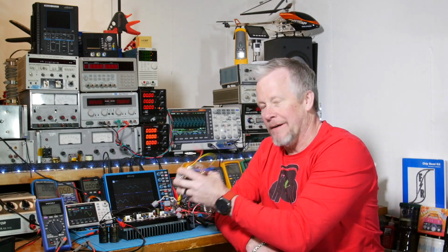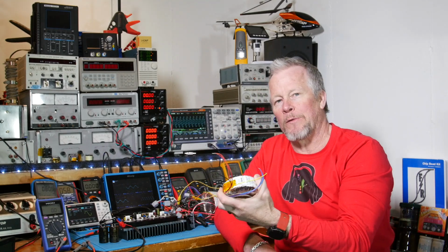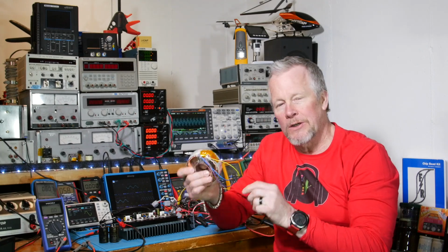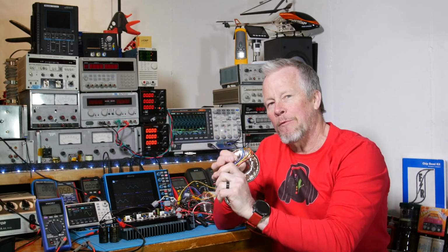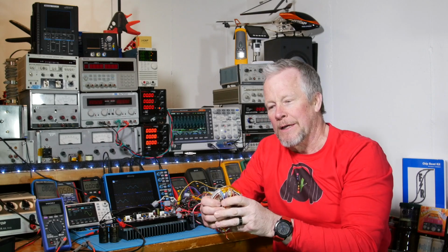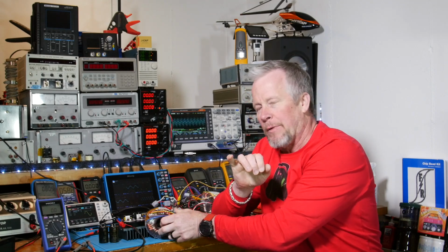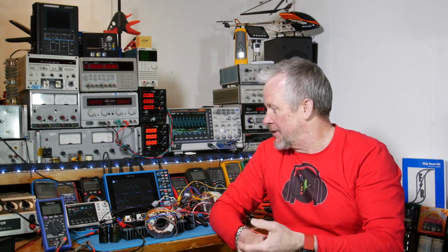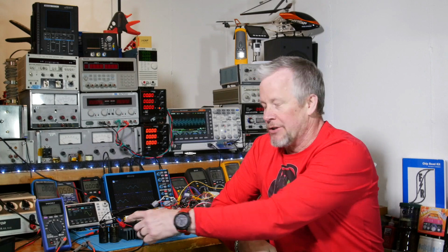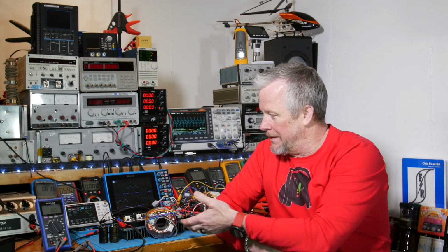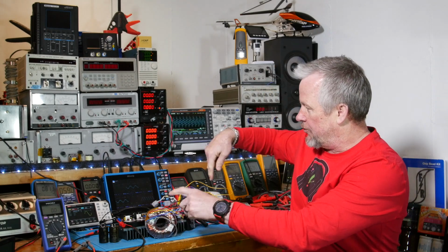Today we're back here at the 20 watt Class A amplifier. What we're going to do is look at some waveforms. When selecting our capacitor and our transformer, we want to come up with the criteria for the design. Is it a worst case scenario at 20 kilohertz or 20 hertz? We want to know that so that we can size the capacitors appropriately, and also decide on one of these two transformers here.